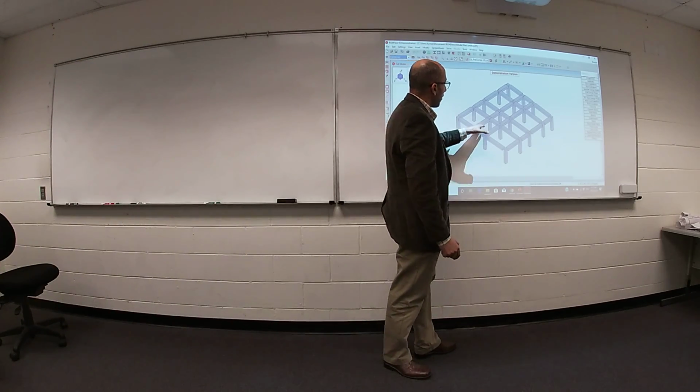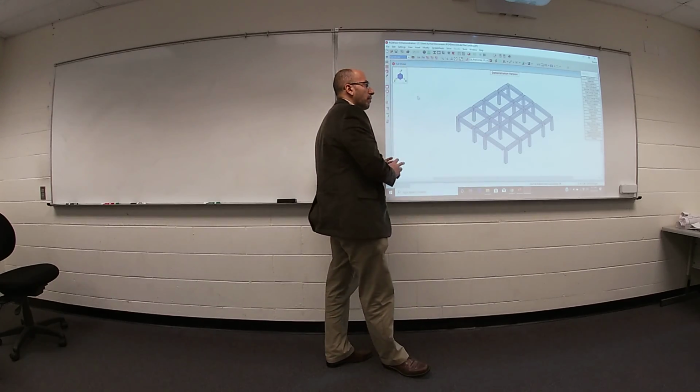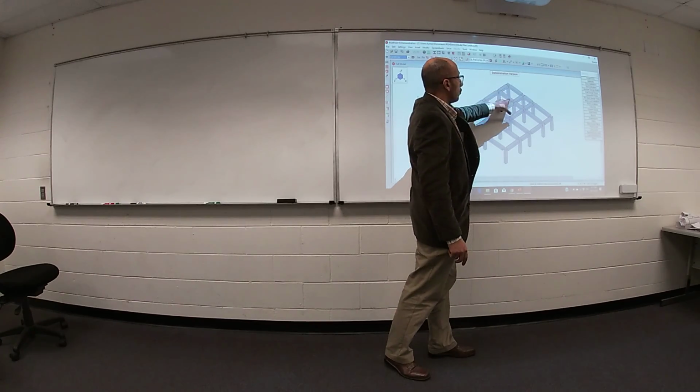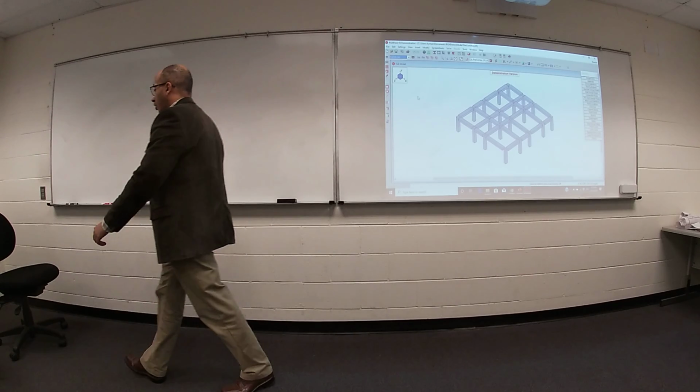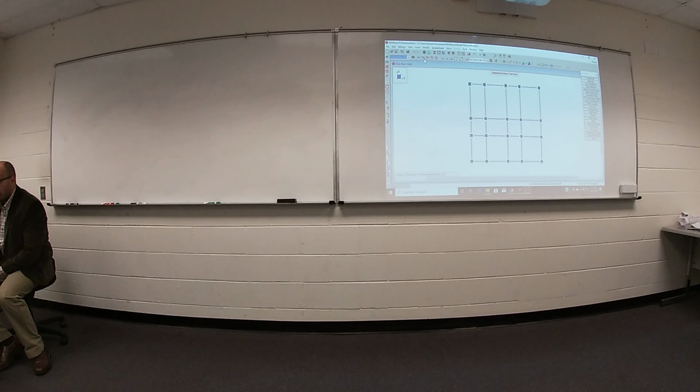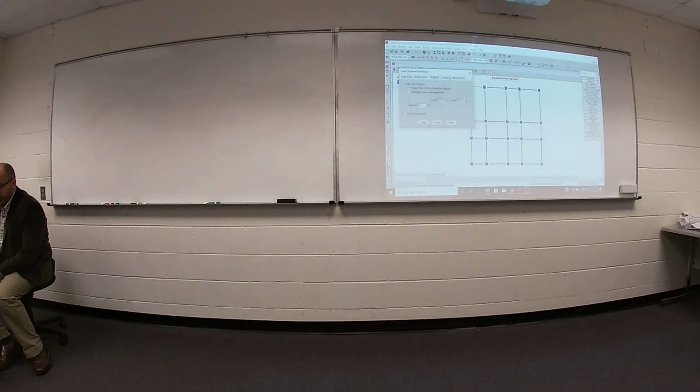So I have my columns, I have my beams, I need to draw my slab. But remember, this area has stairs. So we don't have a slab at this area. So go back to floor plan, go back to plan, and remove extrude view. Insert, where is slab? Slabs. Thickness, your thickness will be 5 inch or 4 inch, whatever. Go ahead and click at each corner.